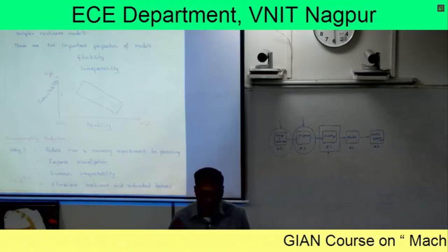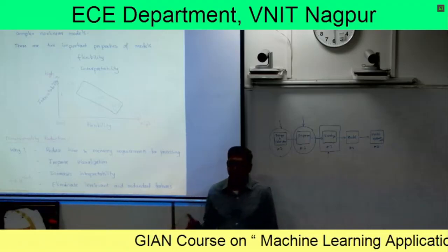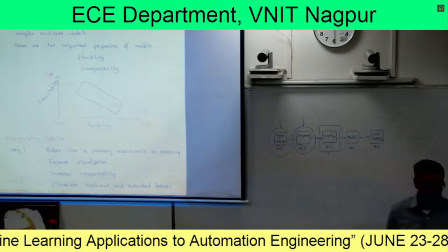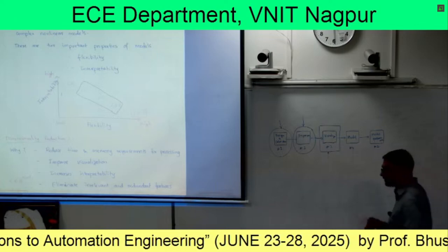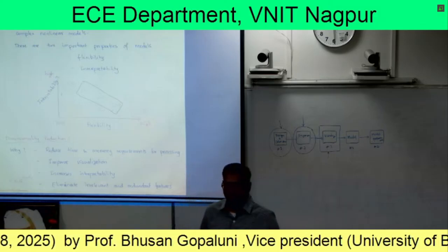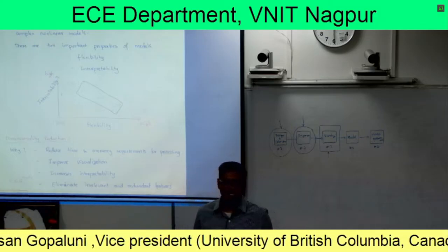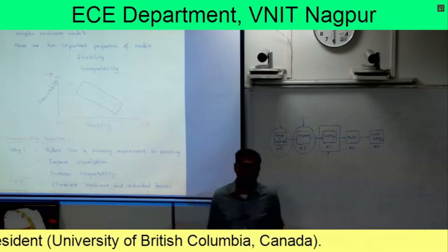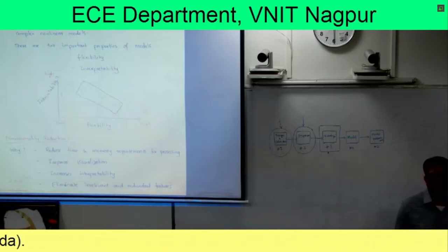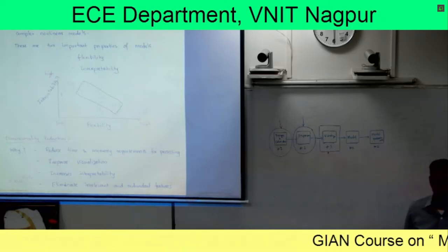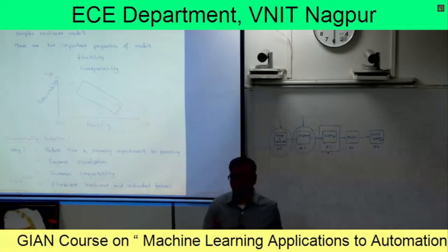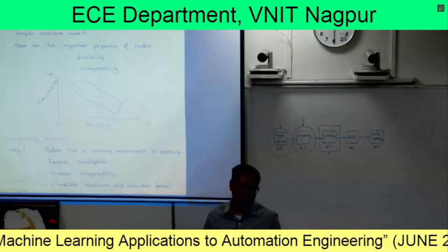If you want a model to design a controller, a closed loop controller, for, let's say, not for set point tracking, but for regulatory control, you're probably going to be okay with a simplified data-based first order model. You don't need a complex, high-dimensional, nonlinear model for controlling your system. You'll be okay by approximating the original complex system with a simple linear first order model, right?